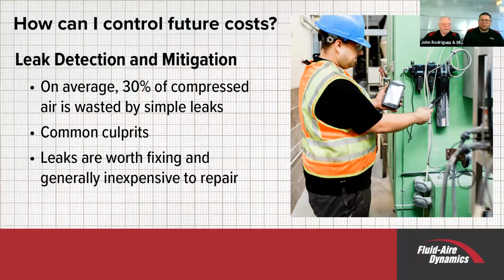Now you mentioned leak detection. Why is this really so important? Again, in pressure, we should talk about that along with it. Leak detection is very important. Leaks will leak again, as we said, the compressed air is very expensive. But if you have higher pressure in your plant and you run, let's say 125 versus 100 pounds, every leak that you have will leak more. So not only are you losing it because of compressed air, losing because of the energy it takes to increase that, but you're using more air because the leak is leaking more air, which is leaking money too.